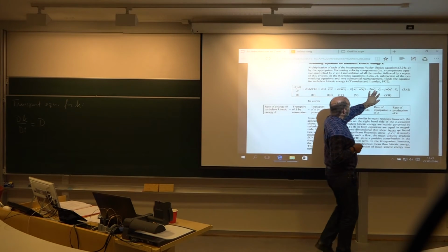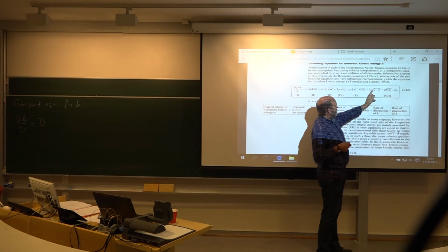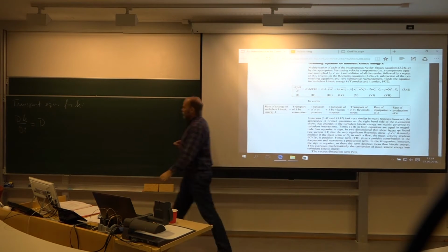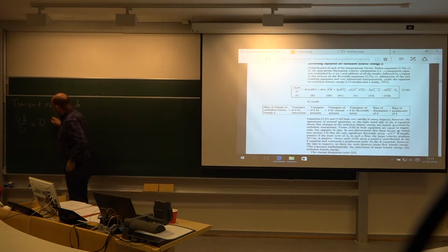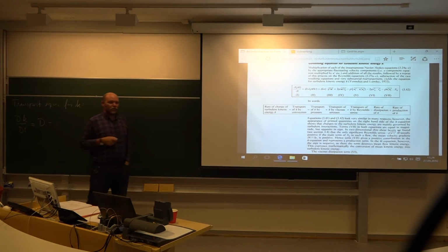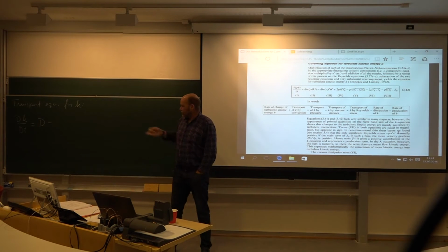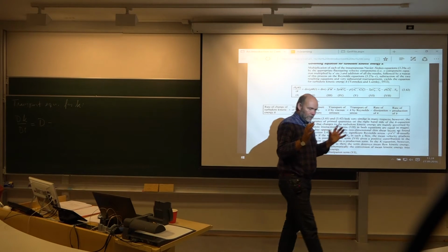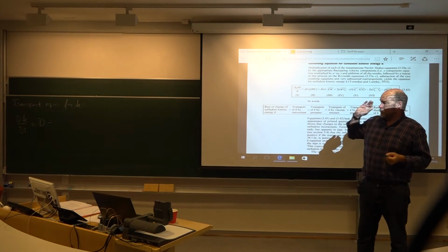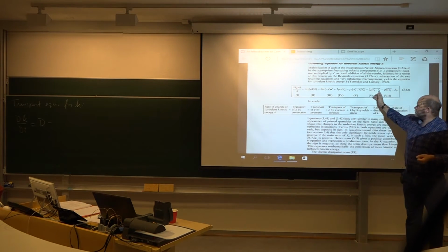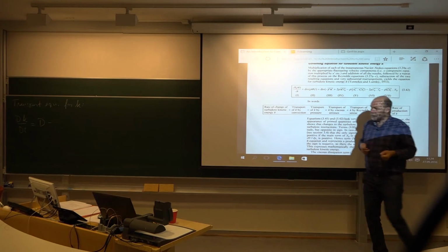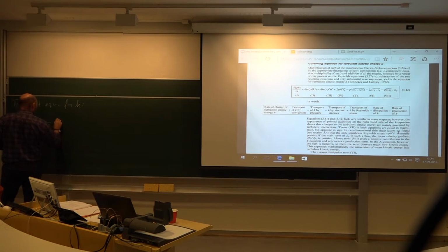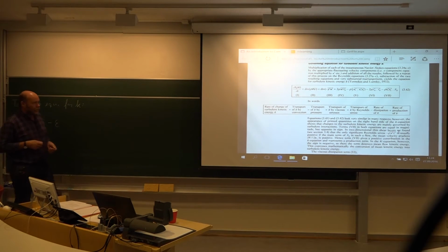Then I have here a term that has a viscosity in front. Viscosity in front, that I will call dissipation. That's something that's going to destroy K. Diffusion can reorganize the quantity inside a given volume. What destroys it? Clearly something to do with viscosity. It will damp down the kinetic motion. So this one I will call epsilon, dissipation.